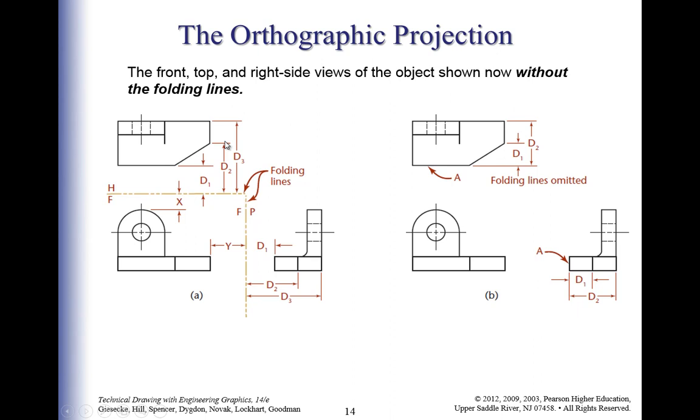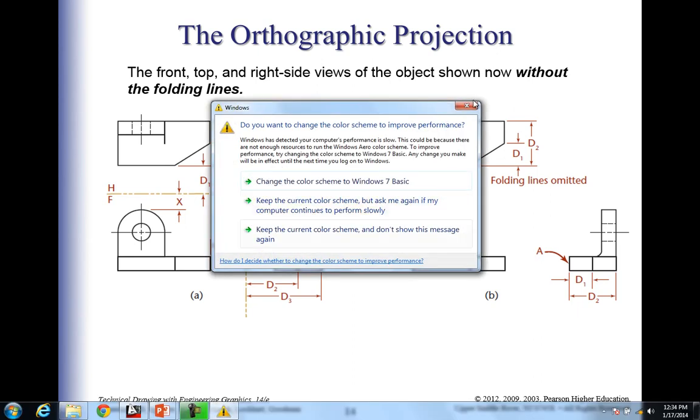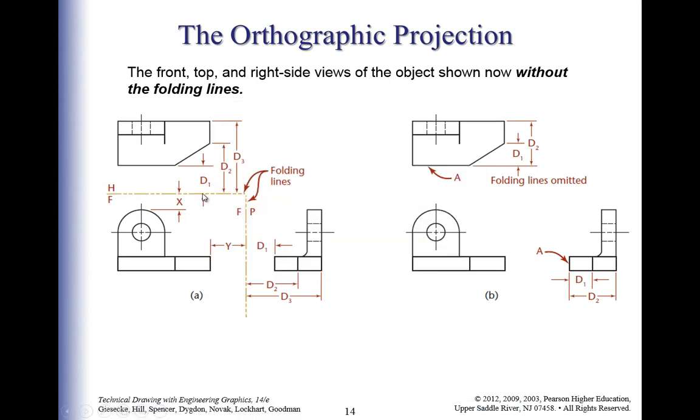And this would kind of maybe clear it up a little bit, and this is in your book on page 168. I want you to really focus on that. You put these little fold plane lines in here, and instead of just placing this view somewhere and placing this one and then bringing a line up and bringing a line over, putting your miter line and then bringing it in, we can actually at this point with that fold plane go from this point to this point, D1, that's exactly the same distance.